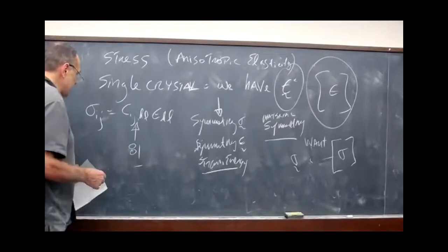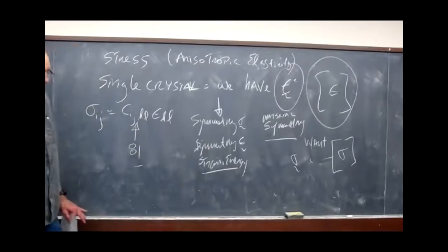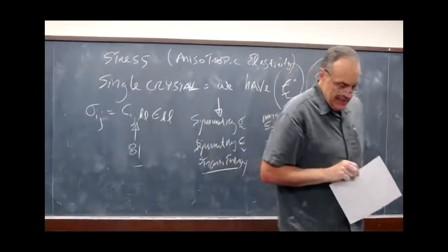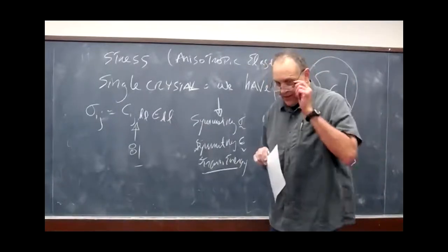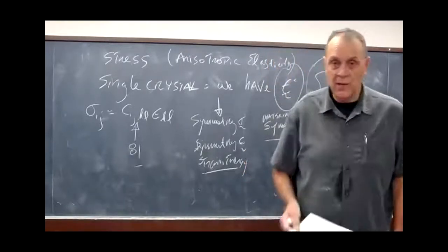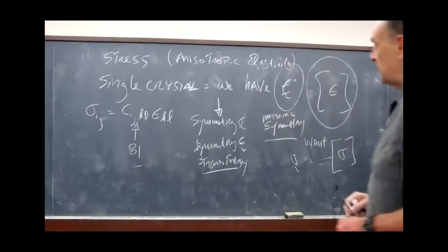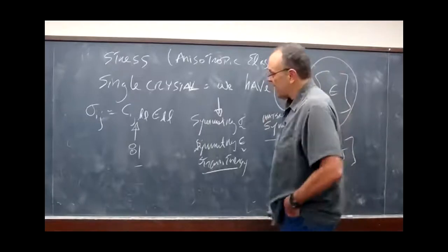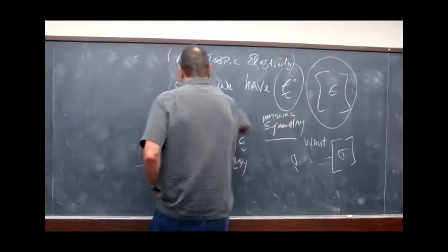So I'm saying that with the strain and this set of elastic constants, I can compute the stress. What about if I wanted to use my experiment to determine the elastic moduli? How would I go about that? Well, again, I always kind of take myself back to the isotropic case.